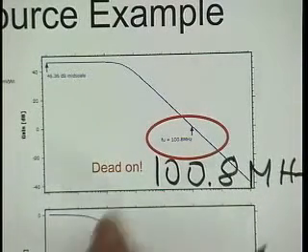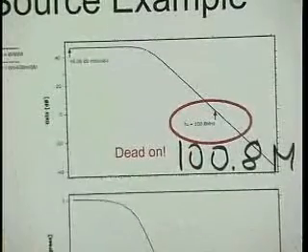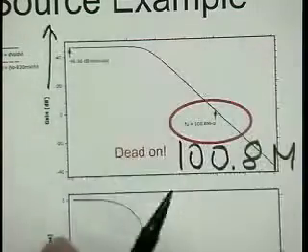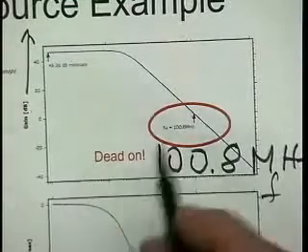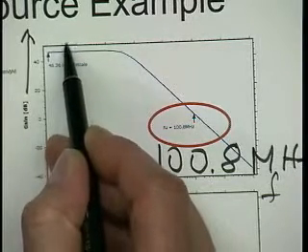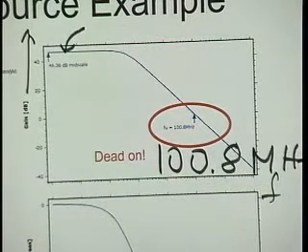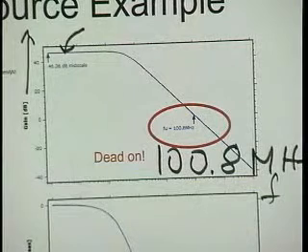Okay, there's also the phase plot. Then the gain. The gain we can figure out in 2 ways. We can figure it out the wrong way and the right way. Here is first the wrong way. This is, of course, an AC analysis, right? Here is frequency, and here is the magnitude response. Very good to figure out what the unity gain bandwidth is of our amplifier. It's not very good, or at least very tricky, to figure out what the open loop low frequency gain is of our amplifier. Why is this a misleading and dangerous thing to look at for that? Why?